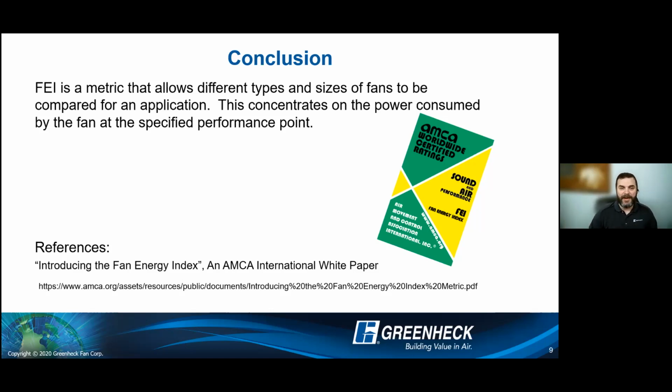Important stuff, but probably not what this presentation was designed for. But the FEI is a metric that really helps us compare fan to fan, right? Is this a good fan for the selection, or is this not a good selection for this application? And it really concentrates on that wire to air, shaft to air theory, where I'm looking at power in versus power out. And this is going to help me grab the right fans at a specific performance.